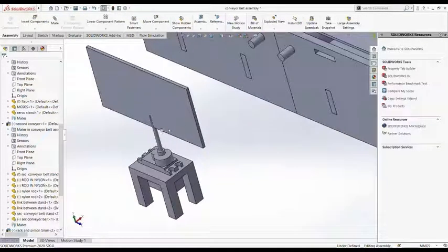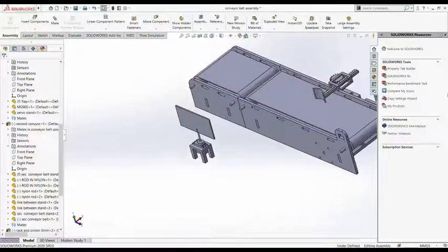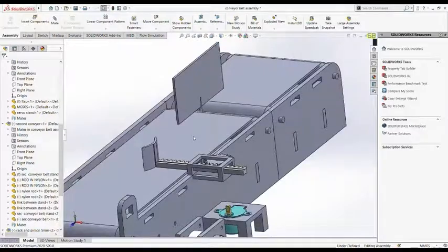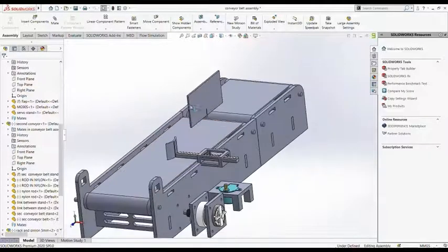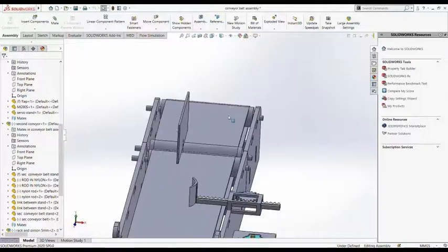This is achieved by connecting the flap to a servo motor controlled by Arduino. From this, the flaps move left or right based on the calculations done by the measuring unit. The flaps in turn push the bottles left or right, and after pushing, the bottles move left or right, and through a smaller secondary conveyor belt they get separated into respective boxes.